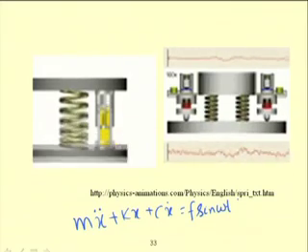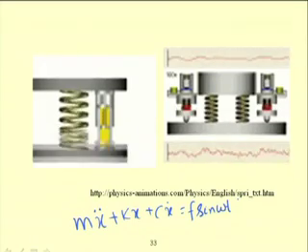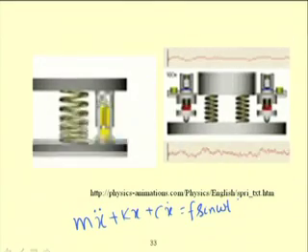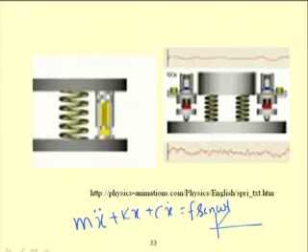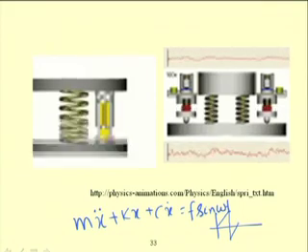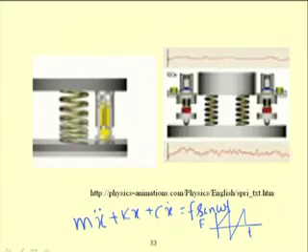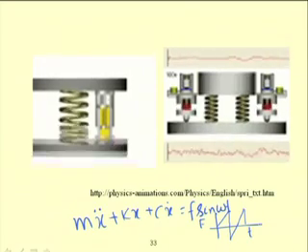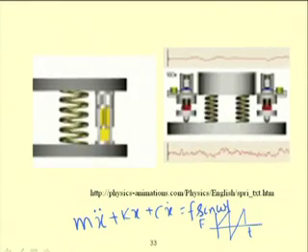Instead of a harmonic force, some other type of force may be applied to the system. The force may be an impulse type of force, it may be a ramp type force, or it may be some other periodic force like a sawtooth or triangular force. This is force versus time, or one may use a bang bang type of force also. In all these periodic cases one can convert these forces into corresponding harmonic forces by using Fourier series.